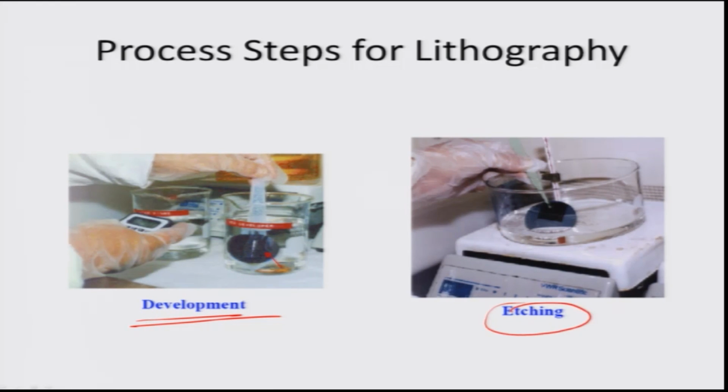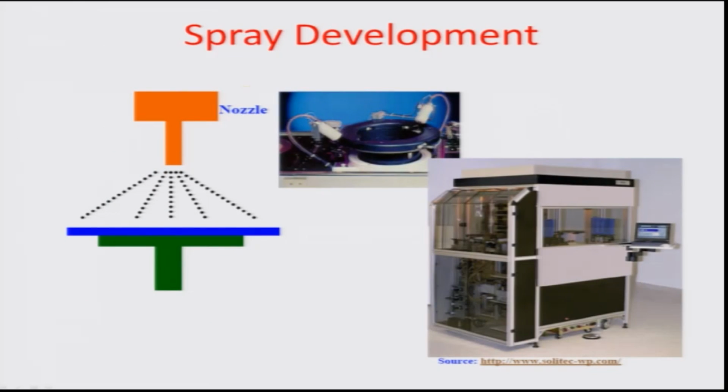Use that as an etch window and further etch the wafer surface, so that you could have features imprinted on different regions. On a high throughput machine, you can do the same by spraying developer solution and by having multiple wafers stacked up and doing this process in an automated manner, more on projection lithography principles.